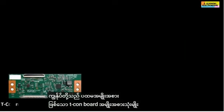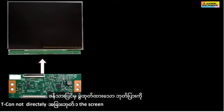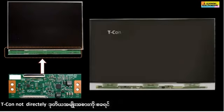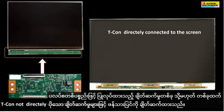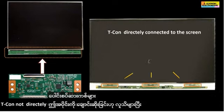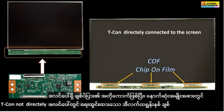In a television set, we can meet three types of T-Con board. A first category with a board separated from the screen. It is connected to the screen via another board. The second category is made of a board in the form of a rectangular rule connected to the screen by one or more connections made of a plastic material on which is engraved conductive tracks and integrated circuits. This part is known as the COF. It is the acronym of chip on film, which means electronic chip engraved on film.